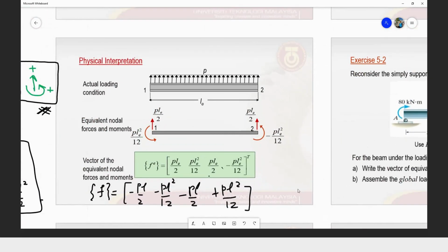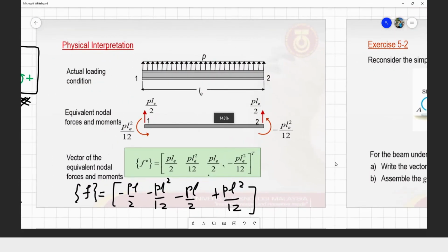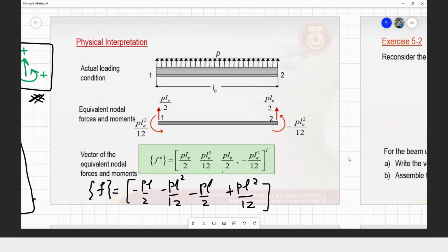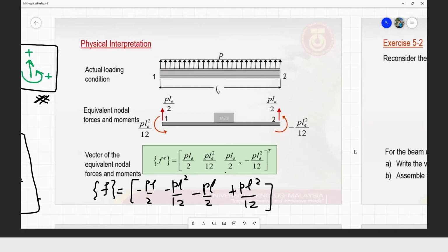You have to understand how your beam is loaded. And then that's it. For concentrated loads and moments, we apply them directly, like we did for the bar and plate trusses, where the concentrated loads and moments are applied to the nodal point itself.